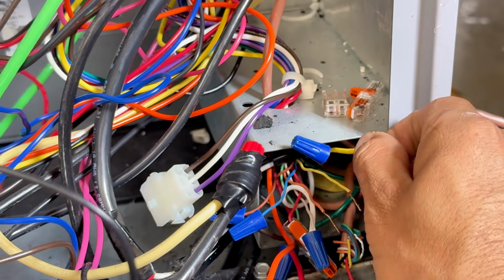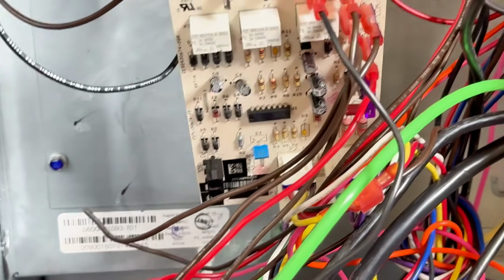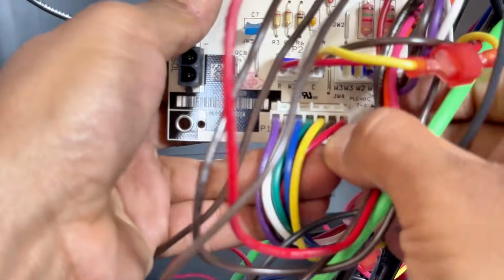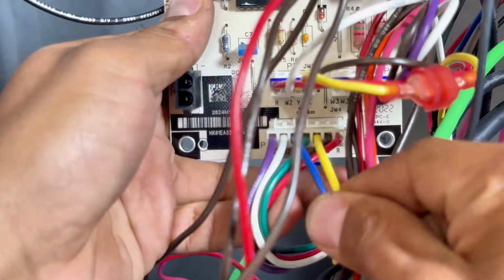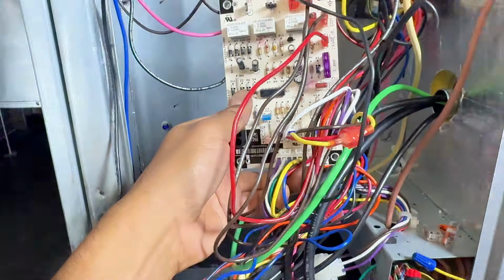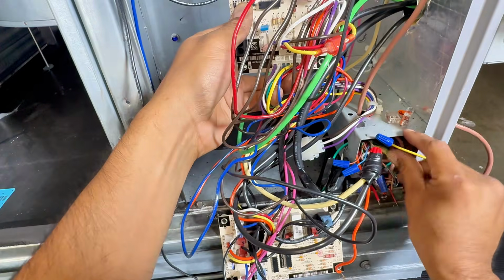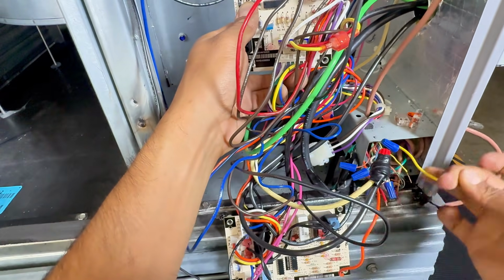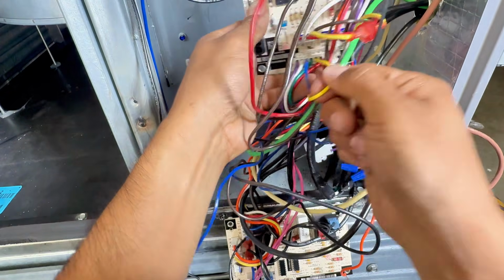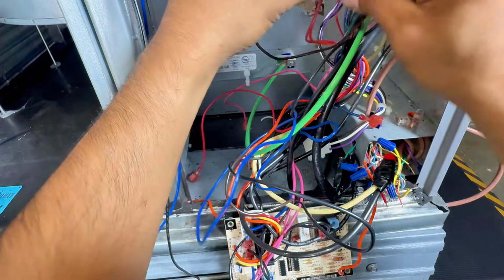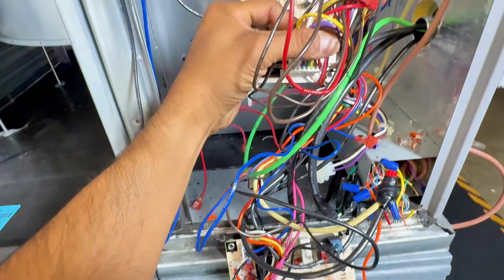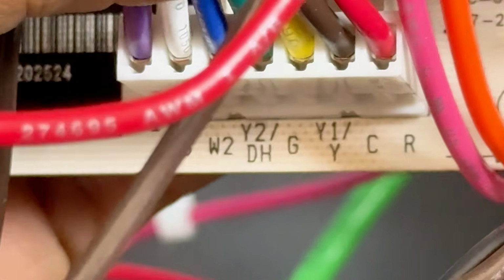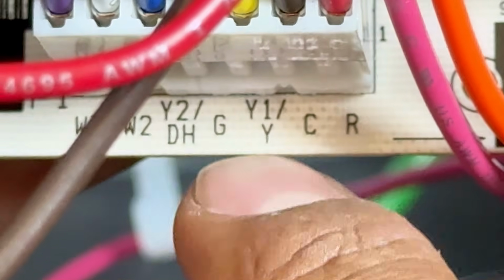Boom, it sends 24 volts to my yellow, and it goes right here. Let's see if I can get a better picture of this. It goes to the bottom of this one right here, right? This yellow wire right there is coming from this yellow wire. If I were to pull, and I have a zip tie there, but if I were to pull, I know it's a little hard, but it's coming to this one right there. And just to confirm, that yellow wire, let's get a little closer. You see, Y1, 1 right there.